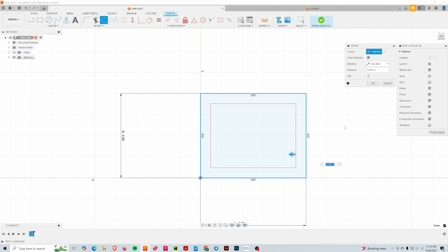If I put M thick, it's going to go to the outside. But since these are functions, you can alter them using signs, numbers, and math. So if I put a negative in front of it, that's my thickness.